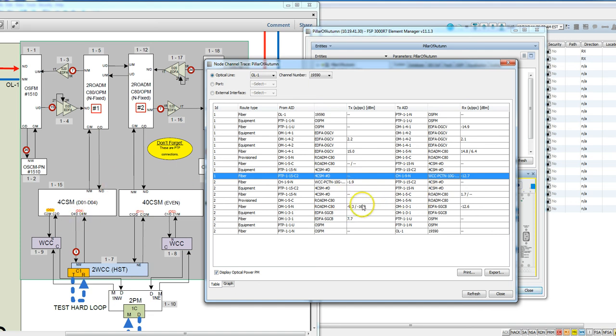Now this would be equalized considering that the set point of that ROADM for its equalization is actually a neg 16. So neg 16.9 is within the offset of 1 dB. So this is leaving that ROADM's network interface as a transmit. In turn, it's going across and it's landing at that EDFA. Actually, this is an error. I actually mean that's 9.3 that it's leaving at. At that 9.3, it takes an attenuation hit between here and here. And so it's hitting that EDFA at a neg 12.6.